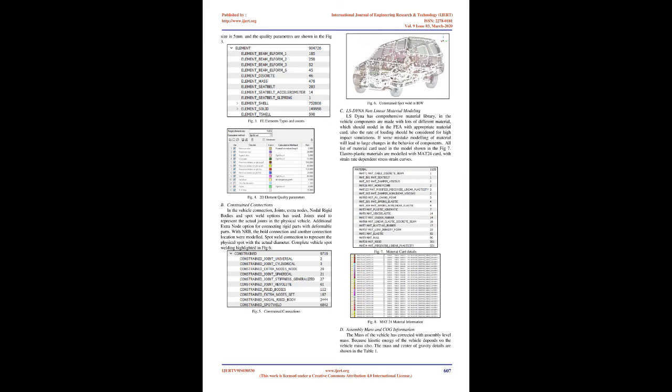2. Finite element model details. The FE model of the vehicle was disassembled and verified with BOM thickness and material information. Full view of the vehicle is shown in Fig 1 and 2. The full vehicle model was converted from the design model to the FE model by using appropriate elements and joints. Element types and quality: the sheet parts of the vehicle are modeled with shell elements, quad and triangular. The meshing is made in the mid-plane of the components and thickness is assigned to those elements, which extrude both sides equally to represent the thickness.